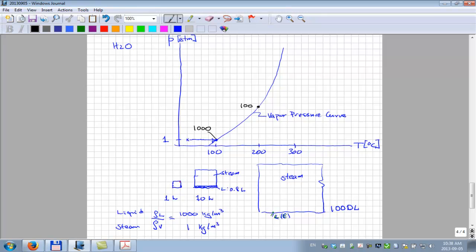Essentially because the gas density has gotten about 10 times higher. It's about 10 kilograms per cubic meter, whereas the liquid is probably still around 1,000. You keep going up here, you finally get to something where there's only a contrast of 10 between the liquid density and the gas density. So this liquid and gas start looking more and more alike in terms of density and viscosity and any other property. Okay?